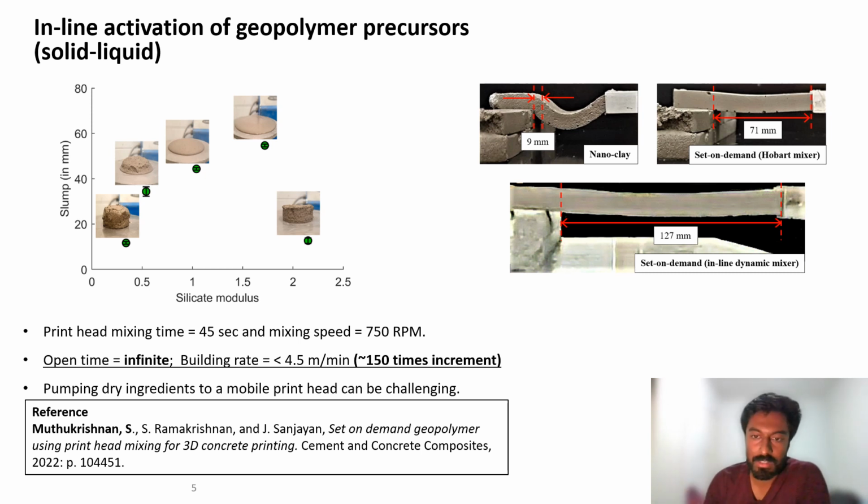We did that study some time after we published this paper. So I guess, if I remember it right, the best operating parameters we have achieved right now are 1100 rpm with a mixing time of 10 seconds. And we got the same mixing efficiency as we can achieve with 5 minutes of mixing in a normal concrete mixer.